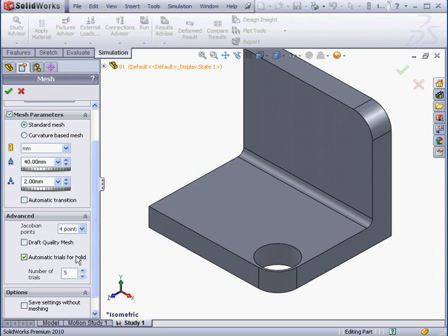Basically, what this option does, when the program encounters an error, it tries to recreate the mesh a second time using a smaller mesh size and tolerance value. The tolerance value specifies the distance at which nodes merge. If the distance is less than specified here, the nodes will merge. In just a second, I'm going to show you where we can set up the size and tolerance factors for these options. For now, let's go ahead and click OK to build our mesh.